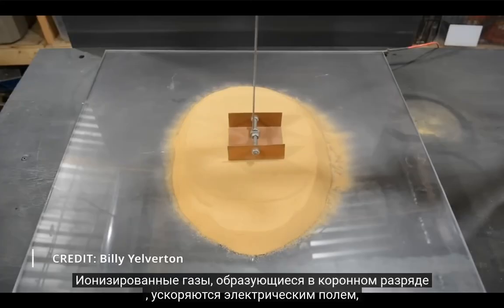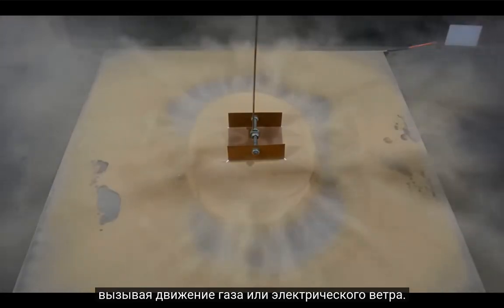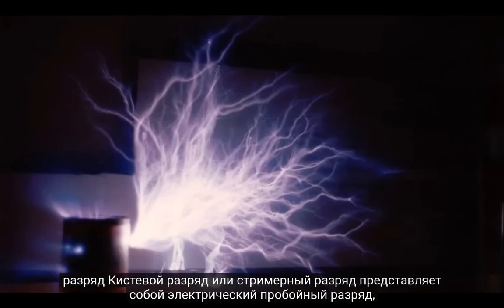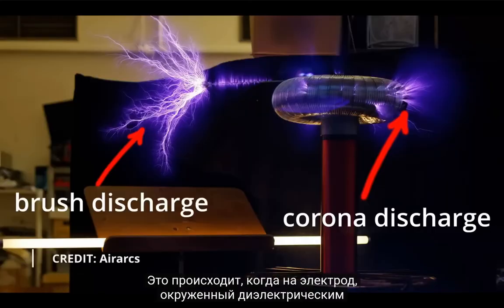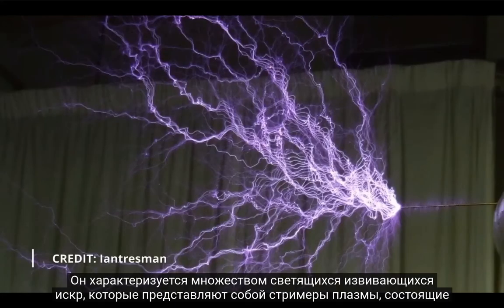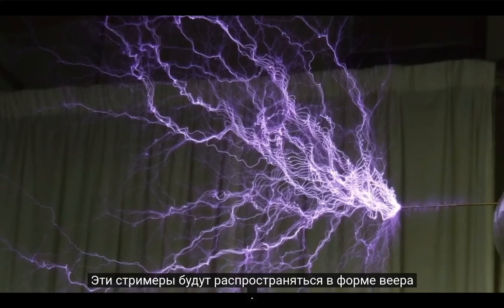Ionized gases produced in a corona discharge are accelerated by the electric field, producing a movement of gas or electric wind. Streamers or brush discharge. A brush discharge or streamer discharge is an electrical disruptive discharge which is similar to a corona discharge. It occurs when an electrode has a high voltage applied to it which is surrounded by a dielectric material like air. It is characterized by multiple luminous writhing sparks which are plasma streamers composed of ionized molecules from the dielectric material. These streamers will spread out in a fan-like shape.